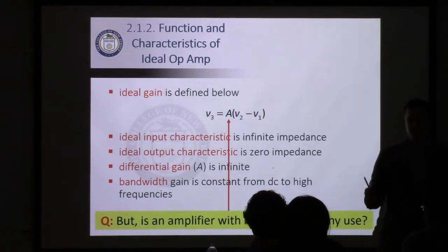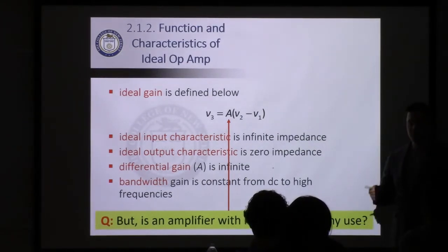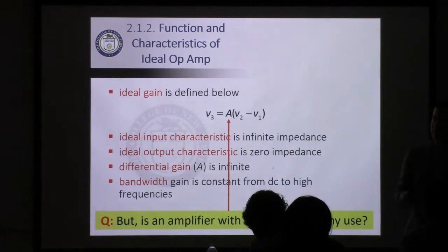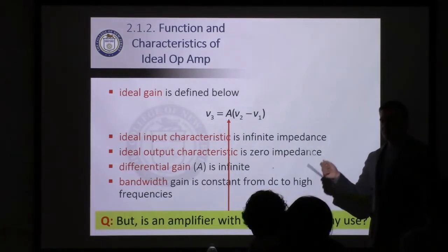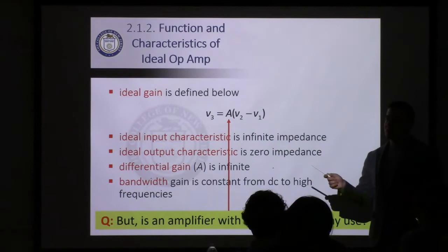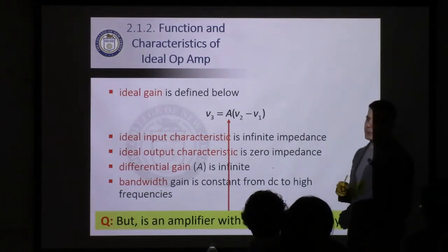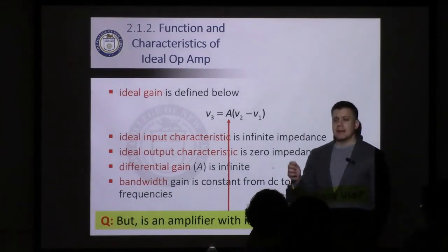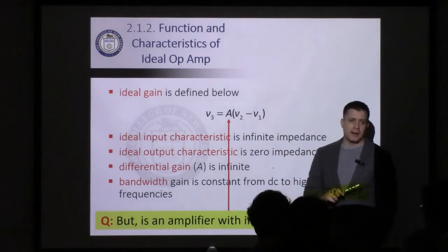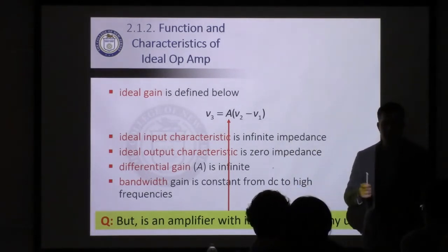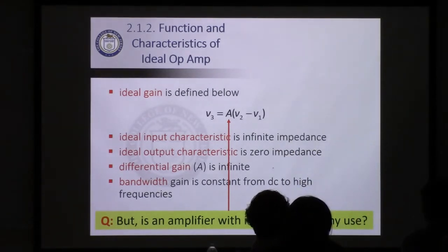So what we do is we take the output, we attach some external resistors, like you said, which provides negative feedback because we connect it to the inverting terminal. That reduces the gain down from an infinite value to some finite value. And the ratio between those resistors is what determines our gain ultimately.